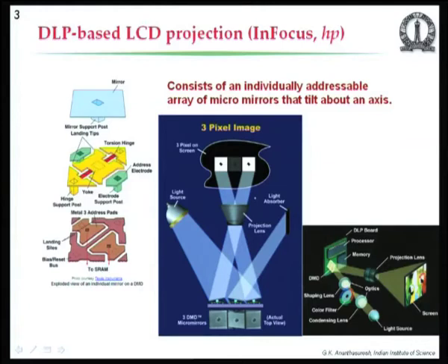For example, this array of micro mirrors which we had discussed earlier in one of the lectures, where we had talked about modeling, where the torsion beam and how to take care of the modeling of the torsion. Now, if you look at this device, there is an array of mirrors, small mirrors, as you can see, the ones that are shown over here, several of them will be there, and they tilt and project the image.